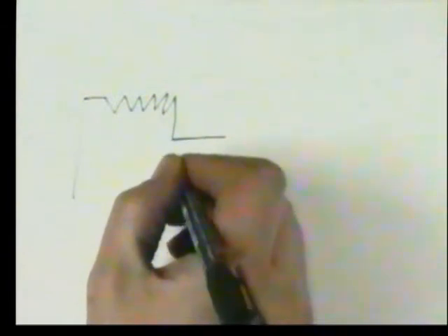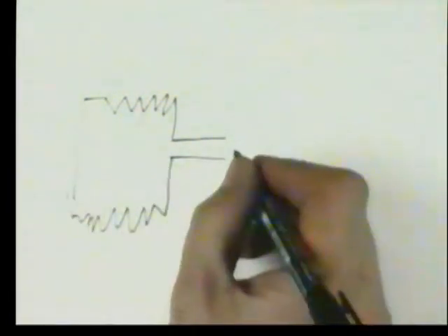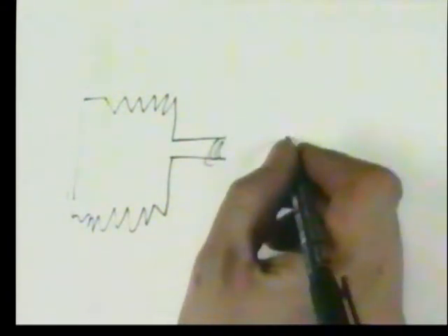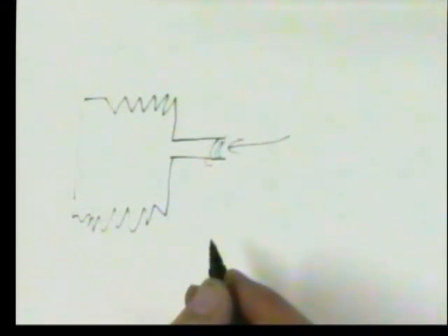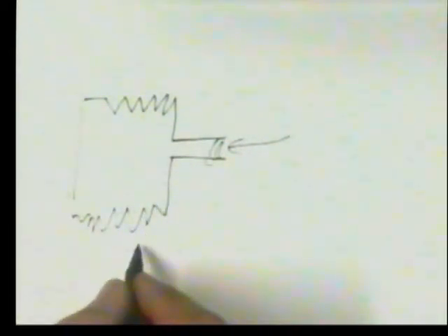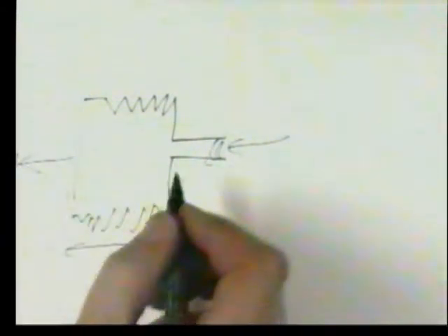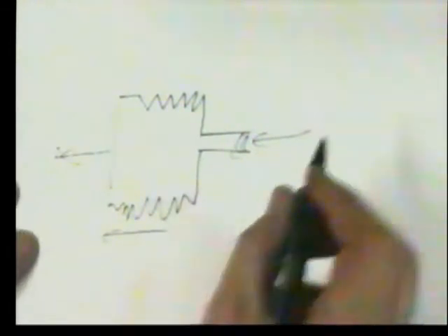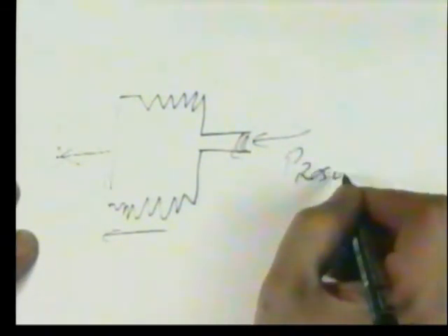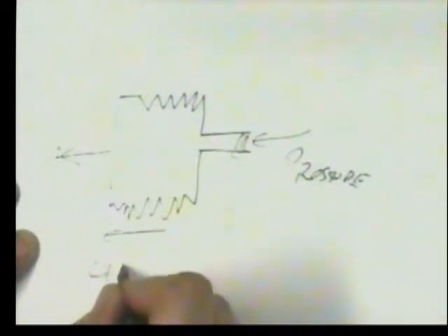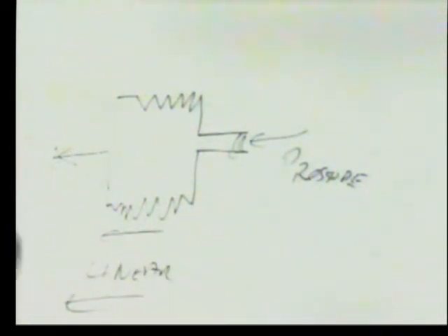Well, it works in a very simple bellows arrangement, except it's done in very thick steel. But think about a small bellows. If you had a little cavity and a bellows such as this, and there's our screw thread, and we apply a pressure into the bellows arrangement. Now, if this was a nice soft material, I'm sure you'll agree, as the thing blows out, it will move and we will get a displacement. So a bellows is in fact a transducer that will convert pressure into linear displacement. That is a transducer.